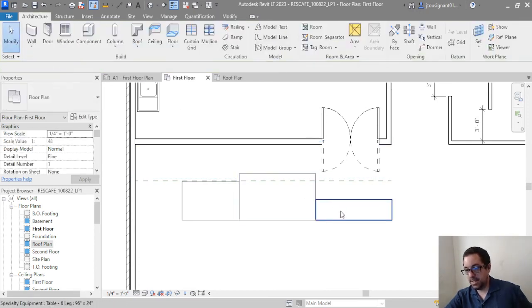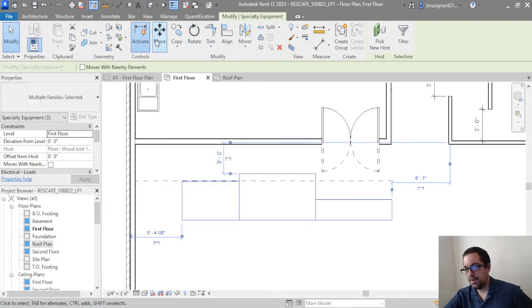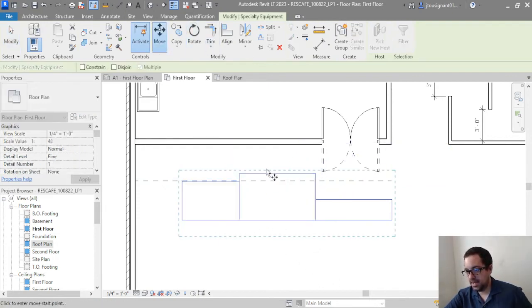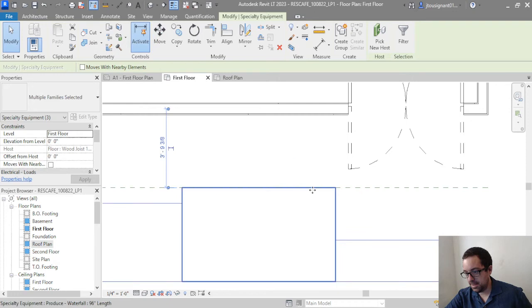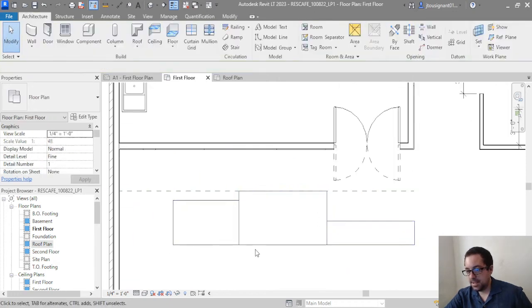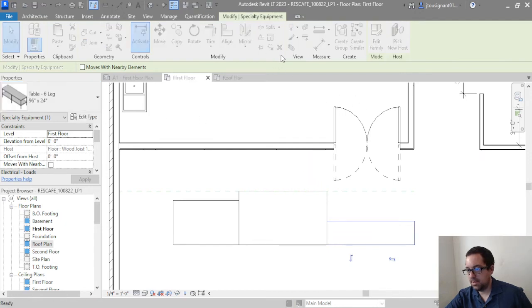So I'm going to select... Do I want to cap something? I'll worry about that later. I'm going to select everything. I'm going to select the move because the fronts are all lined up, and I'm just going to select this back item and move it down to the reference plane because it is the item that is sticking in the most. And now we're good. So now I could probably... Let's just make this a longer table. Let's make a duplicate. Let's make this 96.